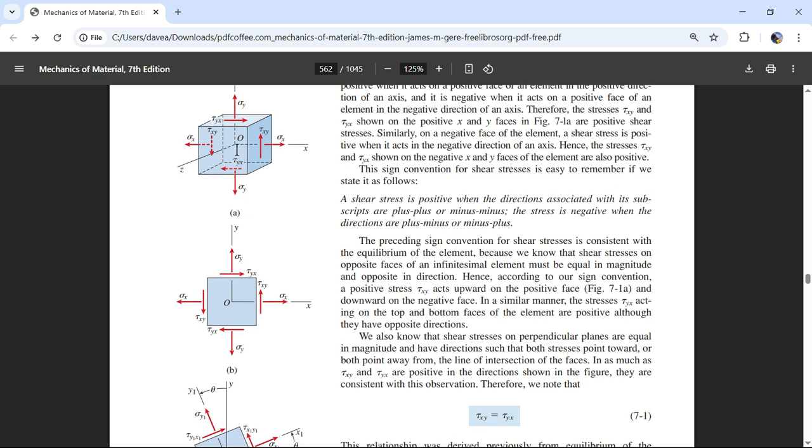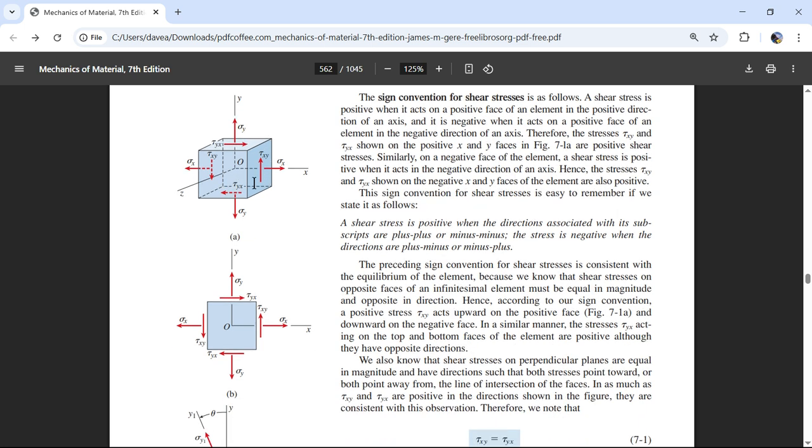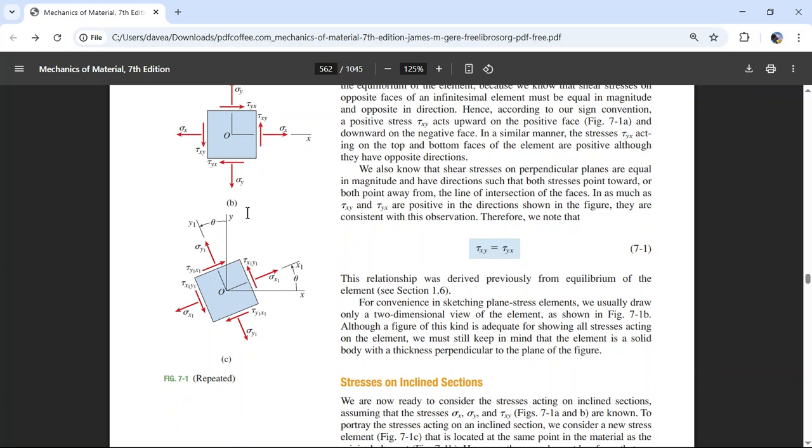If you make it big, and it varies across your bridge or something. But even if it was the Golden Gate Bridge and you're going to cut out a 1-inch chunk of steel, that sounds fine. Not too much is going to go on from this 1-inch chunk of steel to the one adjacent to it. But if your beam is a 1-inch chunk of steel and you're applying forces on it, maybe you'd want to take this to be at least 1/4 of an inch cube, just so your forces aren't going to be changing drastically from one side to the other. Because once we do take a cube, then what we have to have is an equilibrium.